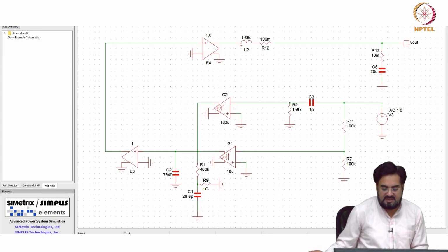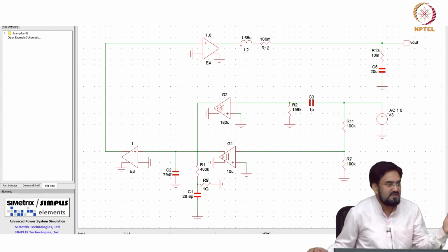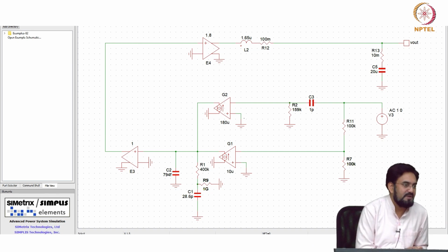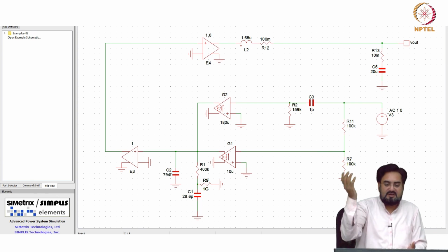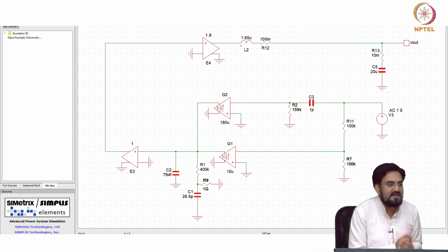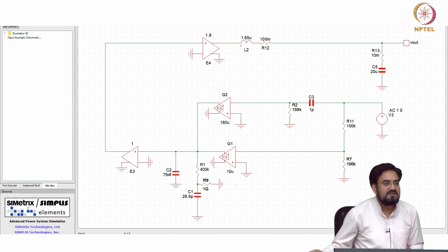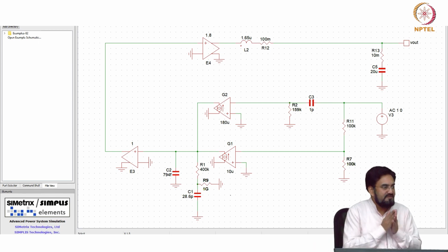So the area also you may get a benefit here, and another advantage is tunability. You can tune simply with the current. You can add a current DAC inside your GM and tune the zeros, which is not possible in the case of an op amp, because you have to tune both R and Cs, which will disturb almost everything, just by simply changing the GM. So you can use a current DAC inside the GM and an R DAC at the RP and tune it accordingly. If somebody wants, let us say your omega naught gets changed, accordingly you can change the zero by simply feeding the digital bits.